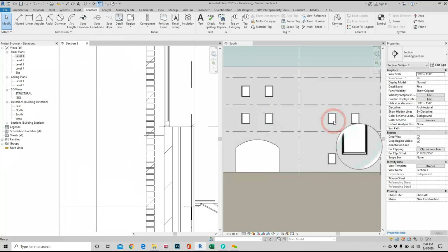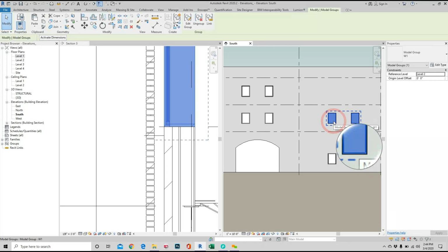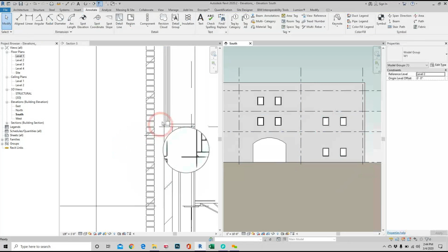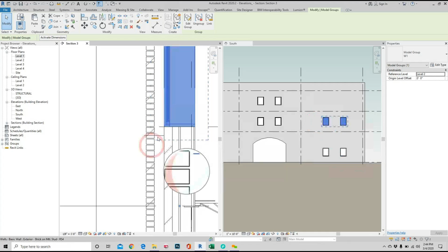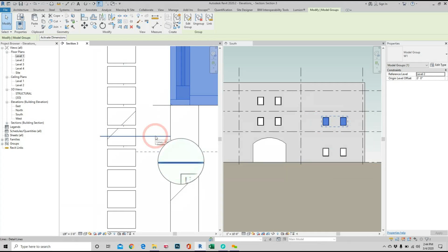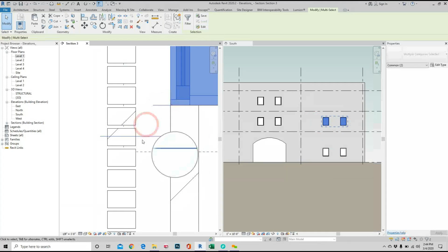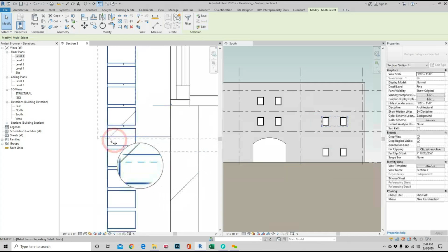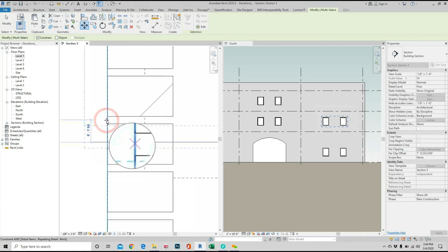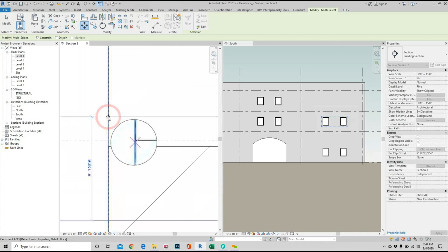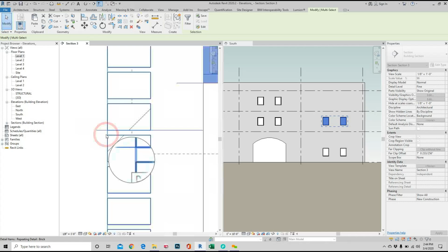You guys should be grouping this thing. So you see, I grouped this guy, right? Because that's what that is. So because I grouped that guy, notice when I select this, I'm selecting that group, right? I'm going to select these lines right here, the 2 that I drew, and I'm just going to move it, MV, and I'm going to say I want this to be at the top of this. And if I'm going to have some mortar, I'll move it a little higher, right, to have the mortar for that sill. So I can go and literally stop it there.